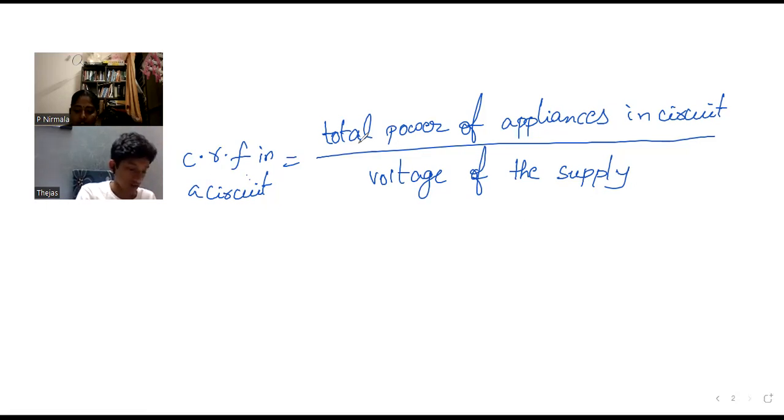With the switch connected in the live wire and switch S in the on position, the appliance gets connected to the high potential point through the live wire. Current flows in the appliance, and the circuit is complete as the neutral wire provides the return path of the current. In the off position, the circuit is incomplete and no current reaches the appliance through the live wire, so the appliance does not operate.